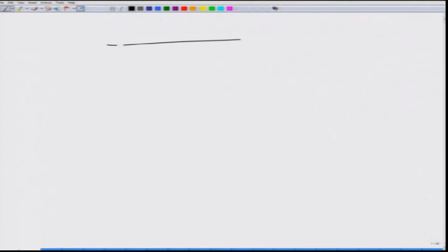Okay. Compared to binary phase shift keying, in which you can write down the constellation point as consisting of 2 points which are separated by a certain distance. Let us say this first point is located at square root of Es, the second point here is located at minus square root of Es. Remember, this is the I and this is the Q component. This is the complex signal space that we are considering, and these 2 points which I have marked by the cross marks correspond to symbols 0 and 1.